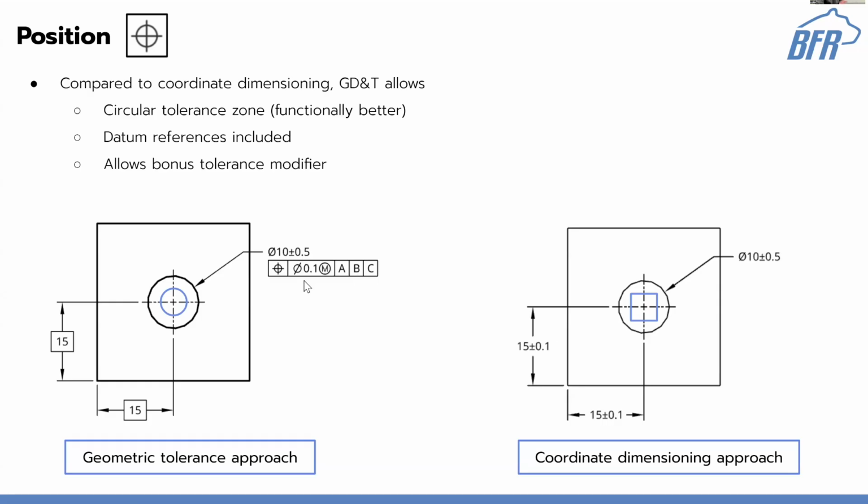And you think it's the same, right? It's 0.1 of a tolerance on all of its dimensions, but the tolerance zone it actually creates is a square, right? Something about squares is not all of its points around the perimeter are equidistant from the center. So a circle, if I put the axis on any point of this circle, it'll be the same distance away from nominal. But if I do the same thing with the square, it's 0.1 inches off if I go this way, right? If it's off in the vertical direction by 0.1 inches, it's 0.1 inches off from nominal.